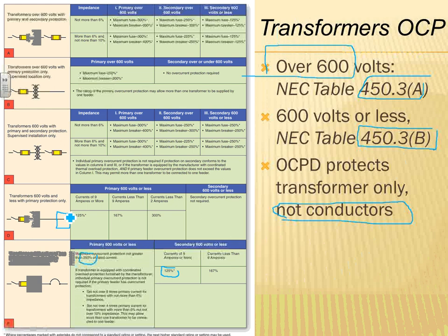You bring the primary voltage, 480 here, 208, and you dump the 208 directly across that machine. No overcurrent device. If you do it this way, with no secondary protection whatsoever, then your overcurrent device on the primary has to be 125.